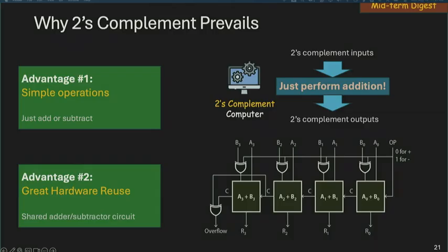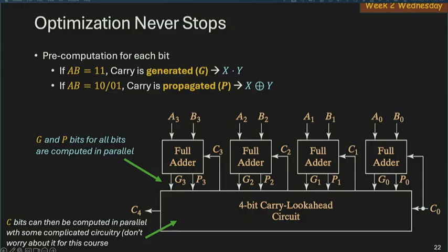We talked about 2-level optimization quite a lot. In real life, circuits have somewhere between 2 and, let's say, 20 levels, maybe 2 and 15 levels. And 128 levels is just so much. You cannot tolerate that kind of latency. And therefore, people come up with some ideas to do some pre-computation by essentially getting all the low-hanging fruits and doing all the computation that can happen in parallel at the beginning, and then develop a large combinational circuit to do all the carry look ahead.